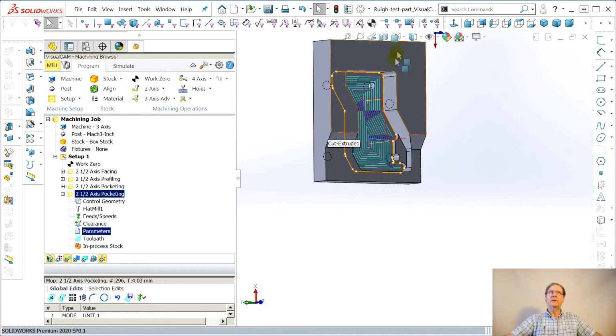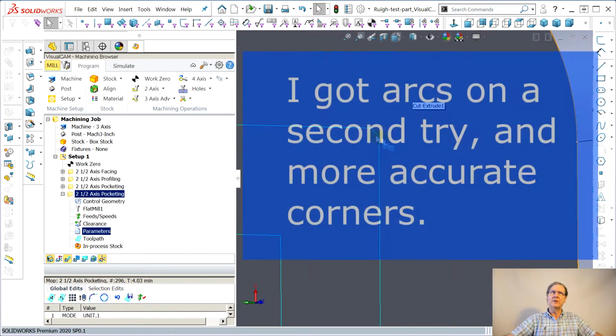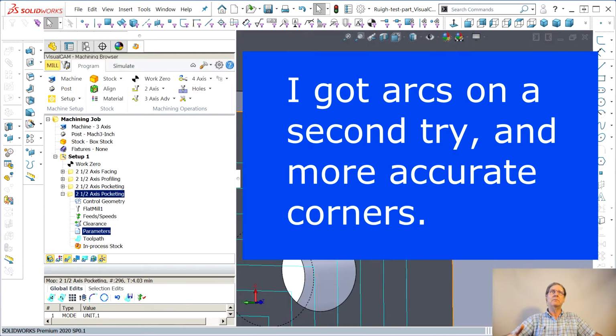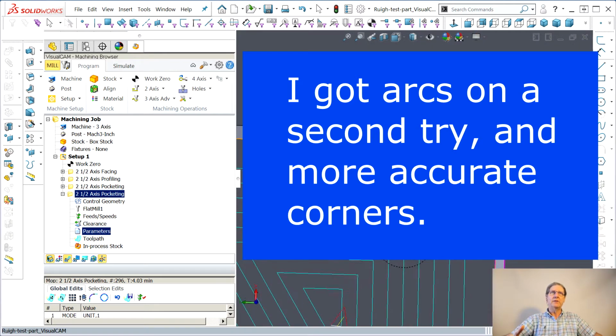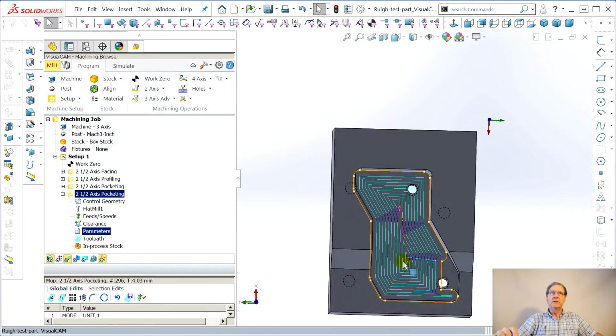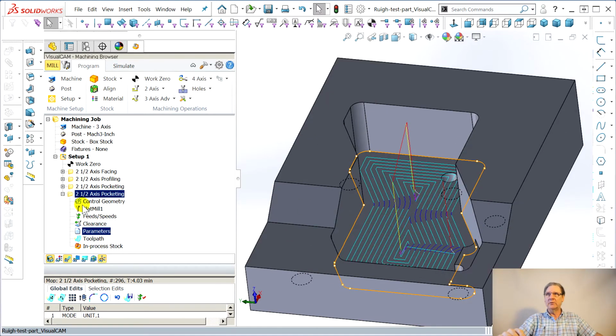And the other encouraging thing is if you look at the corners, it bothers me that they use a hard segment there, but that's rounded. Why? Because my buddy Dave, who made this part, is a genius, and he didn't make these a diameter of 0.25, same as the tool, because then the tool has to go to a point in space, stop, and then change 90 degrees to do the other wall. You make it 0.26 like he did, and now it's a continuous motion, and the milling machine can sweep around that curve. So that's happy stuff, right? We're getting closer. So more parameters.